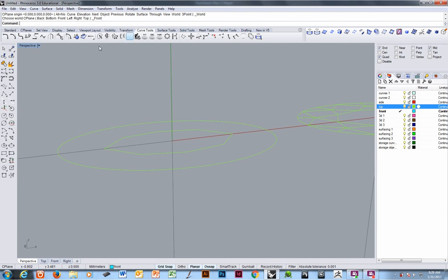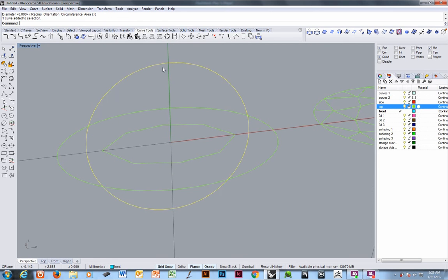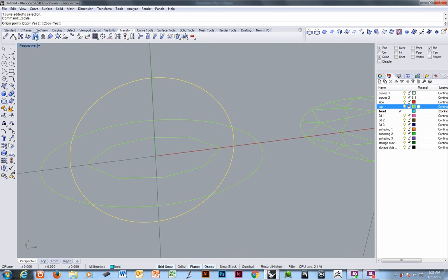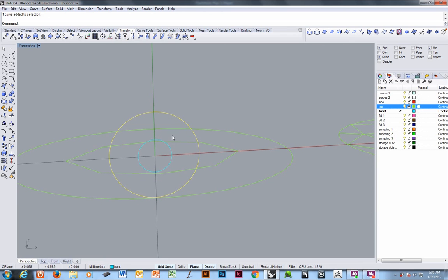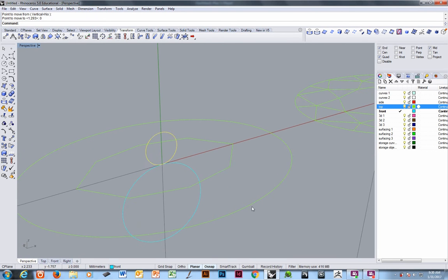So we know this is a 6x8, so I'll make a 6mm diameter circle, and then I'll scale it using the copy option about the center, 0.431 for the first circle, and 0.162 for the second circle. Enter. Delete the guide for the girdle diameter. Move this into position for the pavilion. Go from the top quadrant to 0, and for the crown, bottom quadrant to 0.